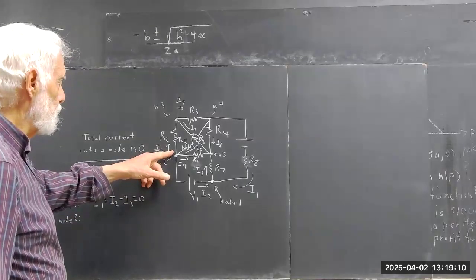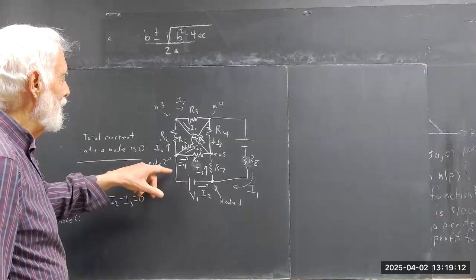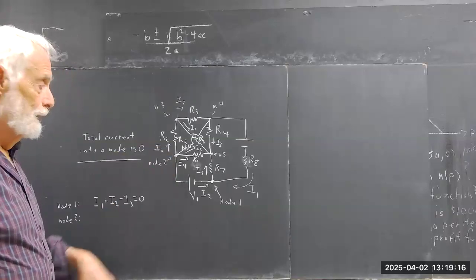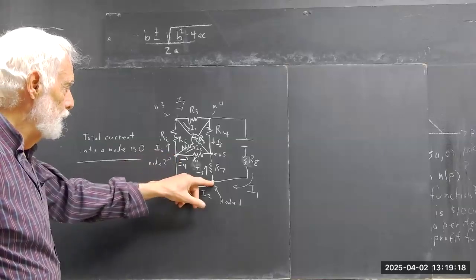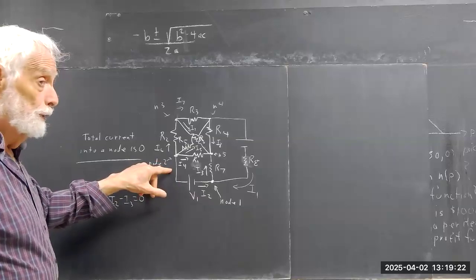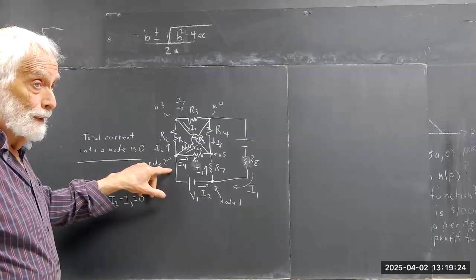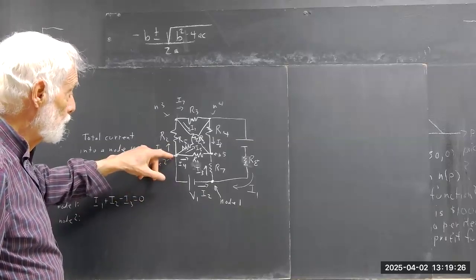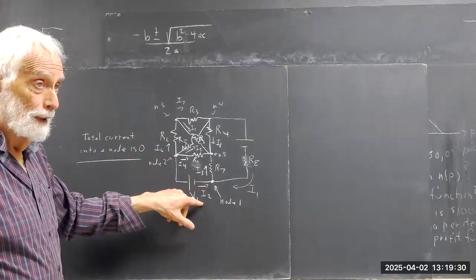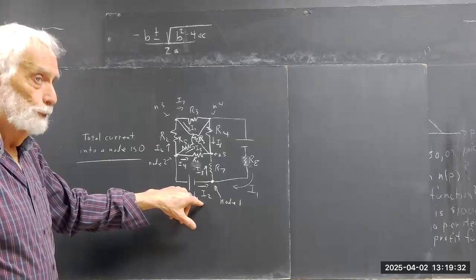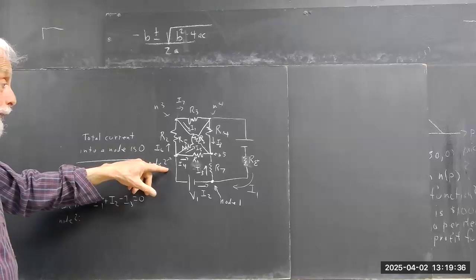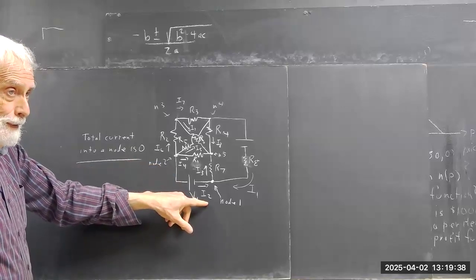There's node 2. What goes into node 2? Well, you don't see anything going into node 2 here, do you? But between here and here, there's no branching point. You got I2 down here. So you got I2 here, right? So if you're looking at what goes into the node, take one branch and follow that branch until you see a current. And if you don't see a current, then write one in. Don't write extra currents, and don't write an I9 here and an I2 here.